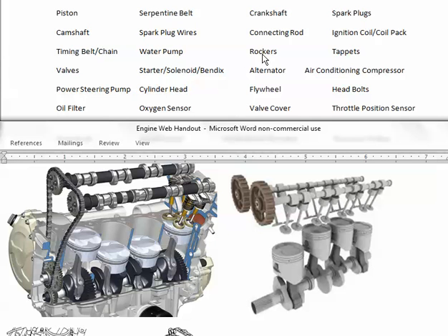The modern version of rockers could be the tappets. A tappet is an upside down bucket, whereas your rockers act like a seesaw and simply get pushed up and down, and it transfers that energy. A tappet directly takes the force of that lobe off the camshaft and pushes down on a tappet. So the tappet will take the force from the camshaft turning and open and close valves.